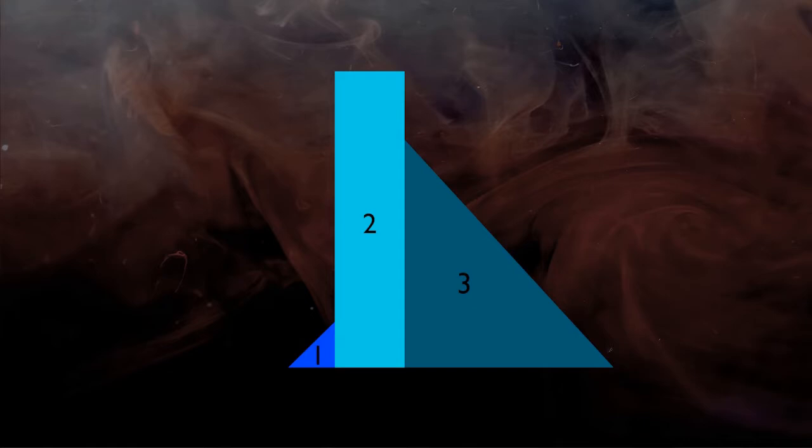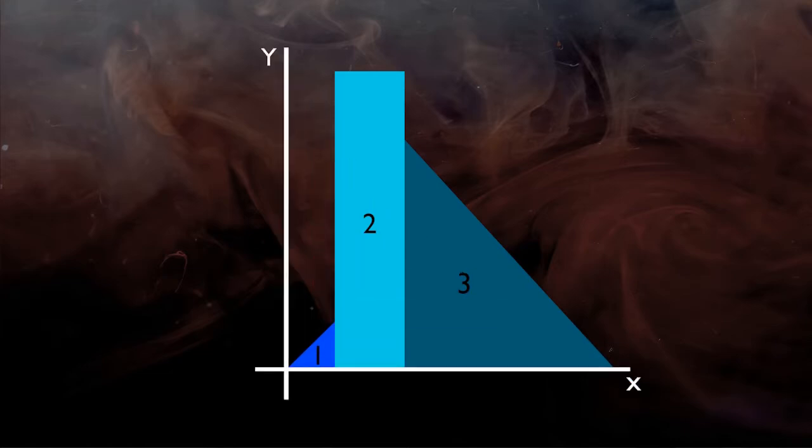For complex figures like this one, I personally prefer to divide the area based on certain rules. Rule number 1 is to keep the number of divisions as small as possible. As you can see, we have only 3 divisions here. The second rule is to divide the whole area such that at least one axis, that is x-axis or y-axis, touches as many divisions as possible. Here the x-axis is touching all 3 divisions. And the third one is that we should be able to find the dimensions of all divisions easily from the given dimensions. These are not mandatory rules, but I prefer it this way.